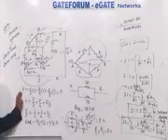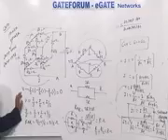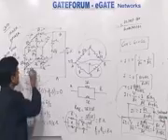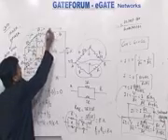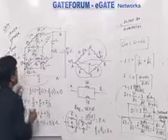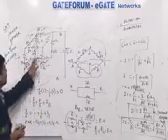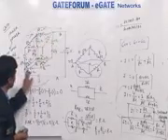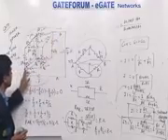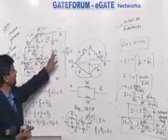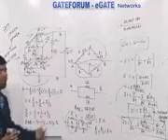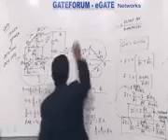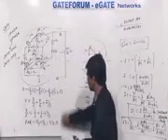Very simple. So in 2 steps only you can solve this example instead of using series parallel combination. If somebody says, okay, I don't want to consider this branch, no problem. You can consider any branch. Suppose I consider this branch, so again I will get the same answer. V minus I by 3 into 1 minus I by 6 into 1 minus I by 3 into 1 is equal to 0. Somebody who considers this branch will get the same answer. So I will get equivalent resistance is nothing but 5 by 6 ohm. So these are very simple examples which are based on the basic fundamentals of series parallel combination of the resistance.